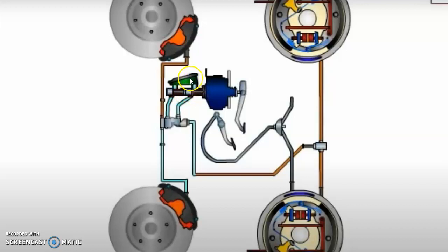From this master cylinder, it is connected through a pipeline to the slave cylinder, or the wheel cylinder. As far as the wheel cylinder is concerned, in construction it is of the opposed piston type, separated by a spring. These are all pipelines which are separated here, and in the front wheel we have the disc type, and on the rear side the drum type braking system. Now let's watch the video of how it actually works.